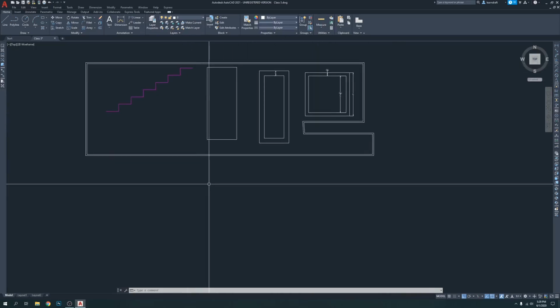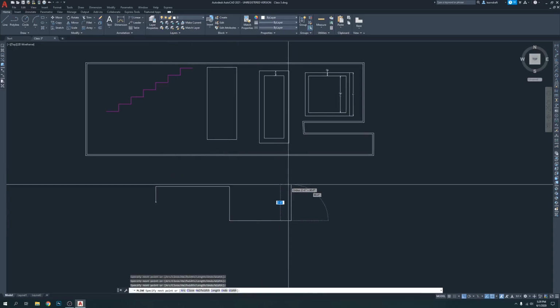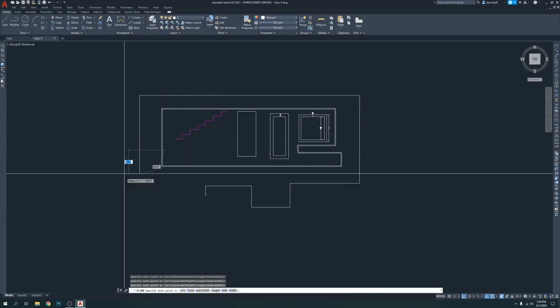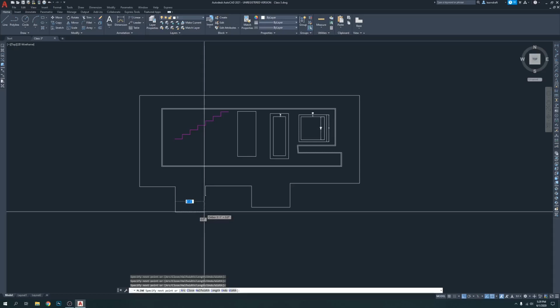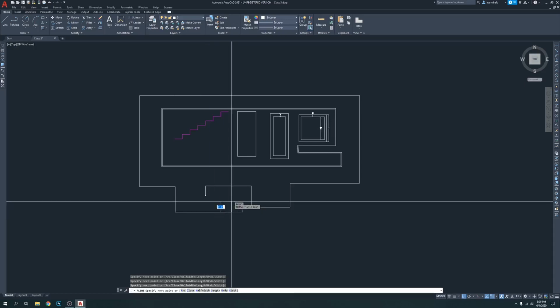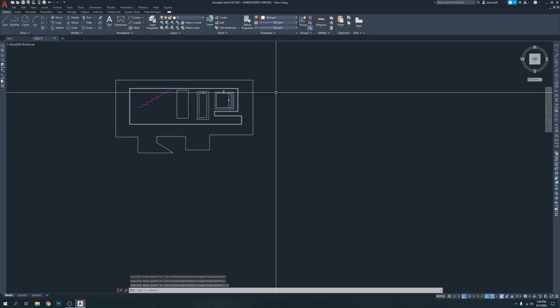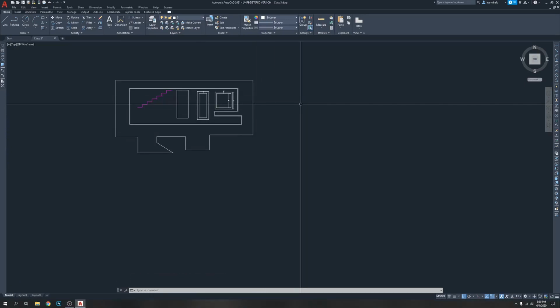If you forget about polyline, let me show you one more time. PL, enter, click, anywhere you go, click, it's gonna follow you the line until you press escape. But I mean, we should practice with dimension. So if you want to do it on dimension, let's say you want to draw a window or a door. Let's say a door, polyline,